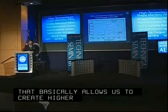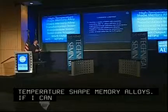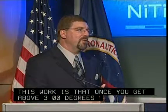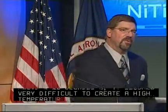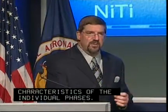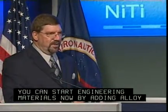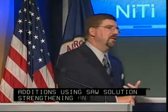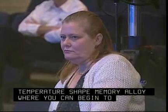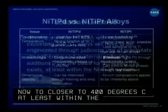So if I could have the next slide. What we've basically found out from all this work is that once you get above about 300 degrees C, it becomes very difficult to create a high temperature shape memory alloy because of the basic characteristics of the individual phases. But there are things that you can do. You can start engineering materials by adding alloying additions, using solid solution strengthening and precipitate strengthening, in order to develop an engineered high temperature shape memory alloy, where you can begin to push the usefulness of these materials closer to 400 degrees C, at least within the systems that we're working with.